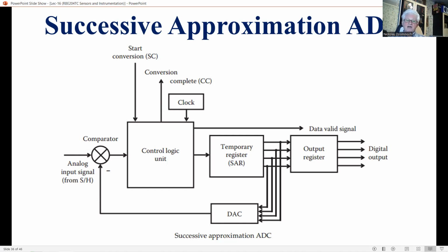Thus far, we have assumed that the value of the analog input signal is positive. If the value is negative, the sign has to be accounted for in the ADC by some means. For example, the sign of the signal can be detected initially from the sign of the comparator output when all bits are zero. If the sign is negative, then the same AD conversion process as for a positive signal is carried out by switching the polarity of the comparator.